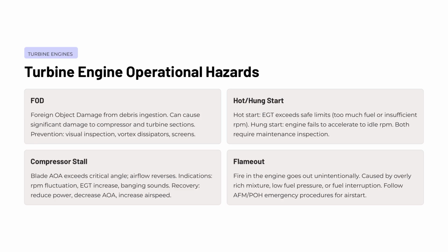Finally, a flameout is an unintended engine flameout. Combustion simply stops. Causes include an excessively rich mixture, low fuel pressure, or fuel interruption. If you experience a flameout, follow your AFM or POH emergency procedures precisely for an air start attempt.